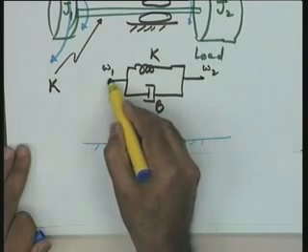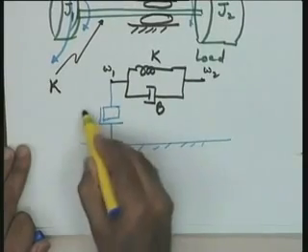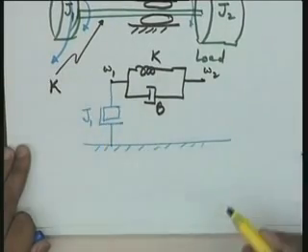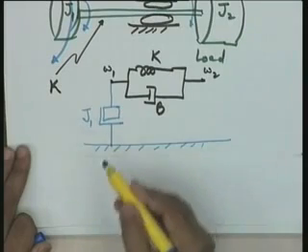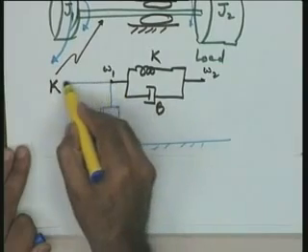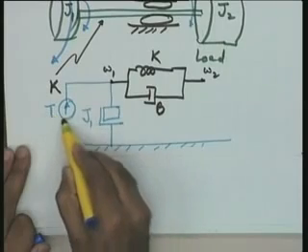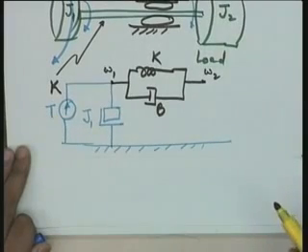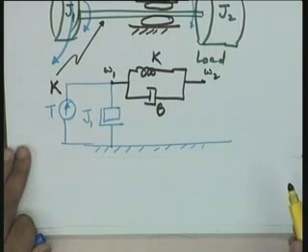In that particular case, this could be taken as a two terminal component, and let me use the same symbol as I used for mass; there is no problem as far as symbolic representation is concerned. So, J1 is this terminal now. Look at the torque T. Naturally, in this particular case torque is analogous to current. So, this torque becomes the force variable, or the torque becomes analogous to the current variable in an electrical network.